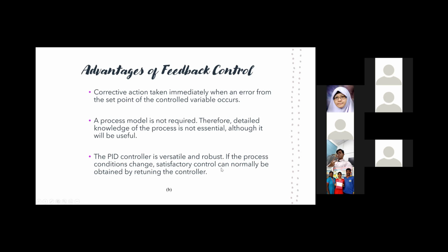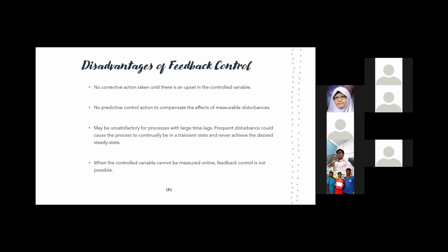So it's very versatile, very robust, you can use it for almost all the processes. There are of course disadvantages. With feedback control, the error has already happened. That means the disturbance or the change has already taken place in the process. Only then do you take corrective action.